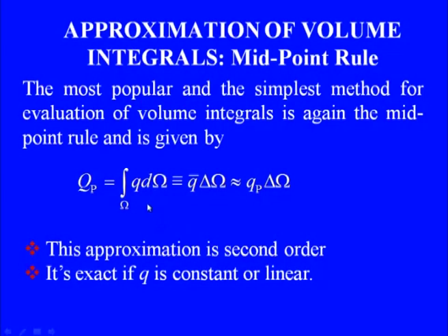Now, once again this simple approximation scheme has second order accuracy. In fact, it will lead to the exact value of this integral if q were constant or linear. So, once again I would like to emphasize that this particular formula, which looks utterly simple, is the one which is used very widely in finite volume analysis.